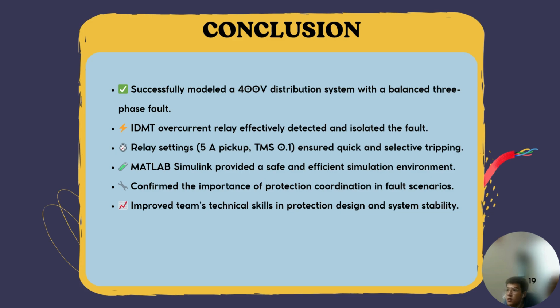And lastly, as a conclusion, our project successfully demonstrates how the balanced three-phase fault can be modeled, analyzed, and mitigated in a 400-volt distribution system. The implementation of the IDMT relay with well-calculated settings ensures a fault is detected and isolated promptly, to prevent system-wide failure.